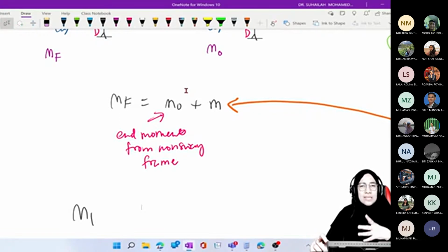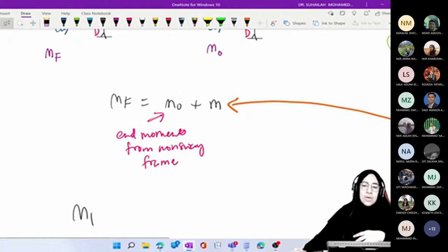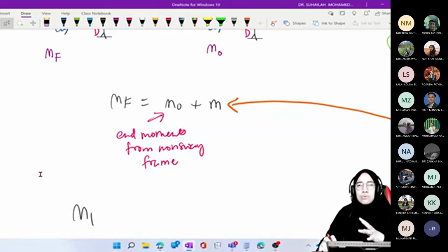So, this is actually what is happening. For a beam we can do a direct solution, but for a frame we cannot do a direct solution because of the unknown delta. So we have to do an indirect solution, which is interpolation between the two diagrams, C and D. We have to make a relationship between M and R, and M prime and R prime.